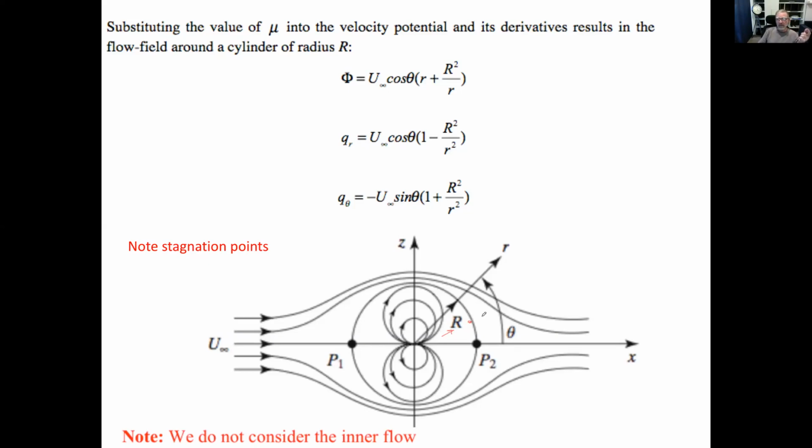And then again it develops, and there are radial directions. So for example, here the radial velocity keeps on going and eventually becomes the same as the free stream on the x-axis, close to the x-axis. So that's what it is. Eventually that will be the velocity potential just by replacing the mu, and that's the nicer way of showing the velocity potential.